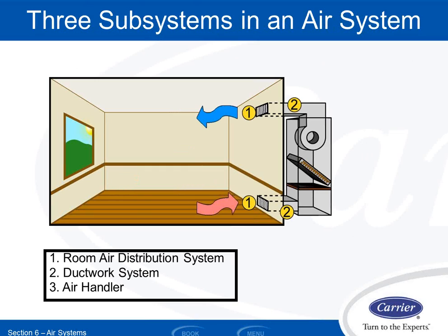In order to move the air, right? I have to be able to draw the air from the room and then deliver it back into the room. So I need an air handler or a fan. I need ductwork to connect these systems.